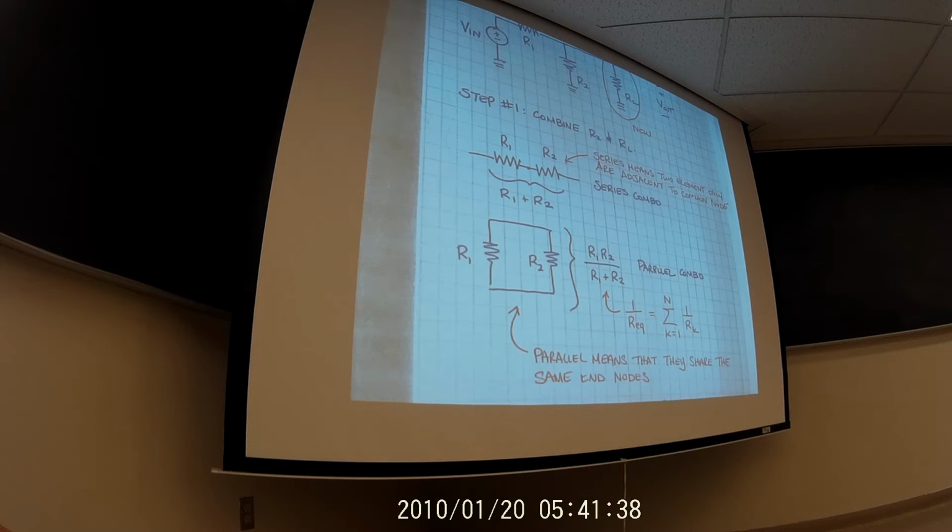When you combine 2 resistors with the same value, you end up with half of them. Parallel combinations of resistances always make the resistance go down. So whatever the lower resistance is of the two, no matter what you combine it with, you're always going to end up with, at best case or highest, that lower resistance and lower. It's never, a parallel resistance is never going to make that equivalent resistance go up.